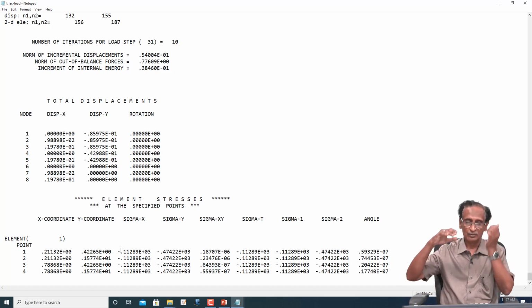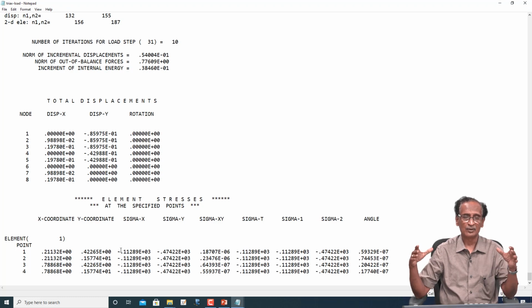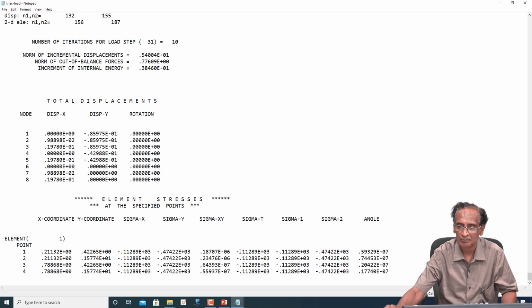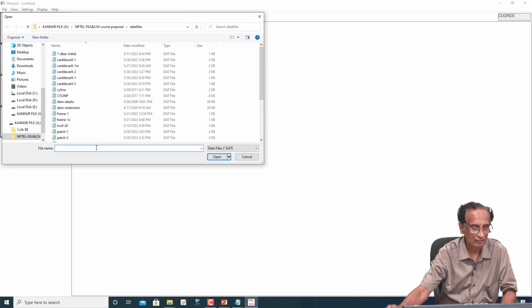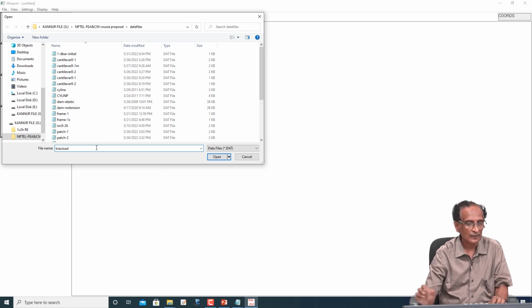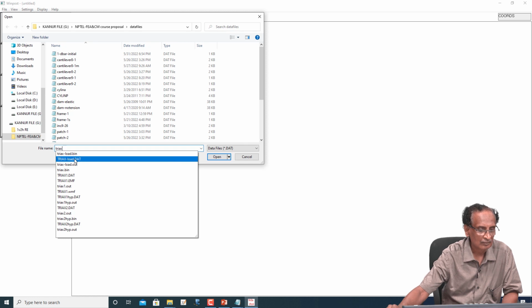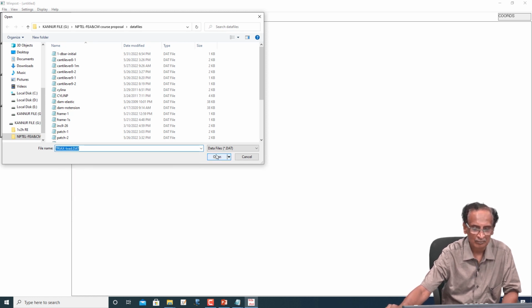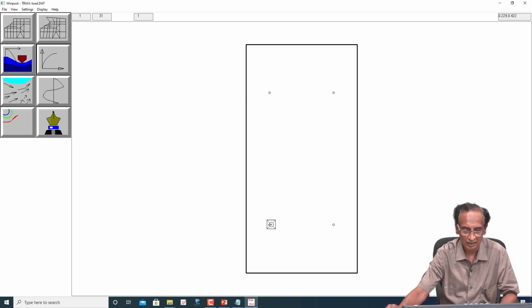So this is what we see if you go on applying vertical pressure: because of the stress correction procedure, the lateral pressures will go on increasing. Let me illustrate that through this program. See this, there is a data file called Triaxial load, corresponding to load control analysis, and let me just set this. Let me plot how the stress strain curves are changing.